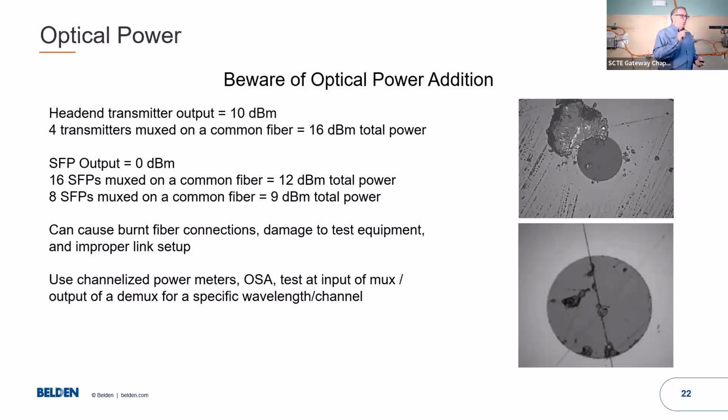So we had, once again, in the head end, when you're working on the large muxes, problems with burnt out fibers because people would preload everything and then go to the patch panel and put it in. And sometimes we try to clean them, you scope them, and they just won't come clean because of the burn and the damage that was done to the end of them. So paying attention to what you're working on will make a big difference.